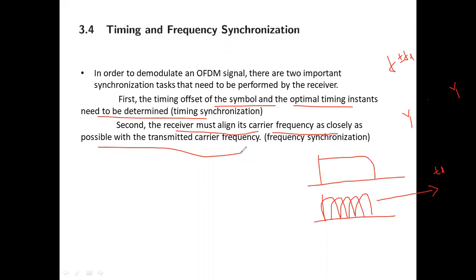You have an audio frequency oscillator at the receiver with the same carrier frequency as at the transmitter. Both of them should be in phase. That's what PLL does: it matches them in phase. That is when the demodulation occurs. If they are not in phase, then we do not have frequency synchronization, and there will be a problem. Let us analyze these two issues individually now.